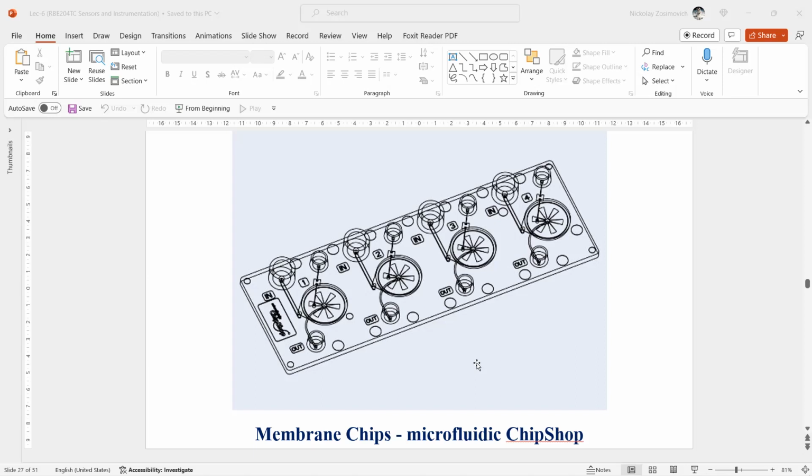A larger capacitance may be realized by reducing the gap distance between the plates. However, electrostatic or attractive forces between the plates can easily result in buckling and short circuiting of the capacitor. The alternative is to increase the effective surface area, and this can be realized by supporting dielectric structures.